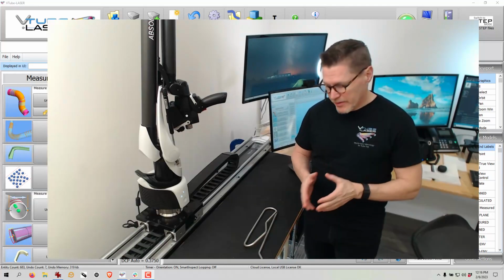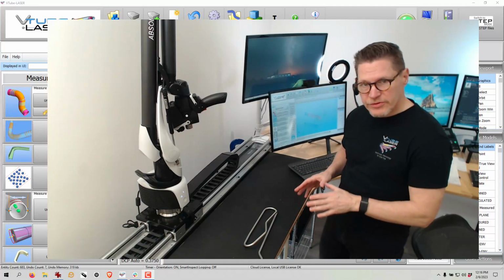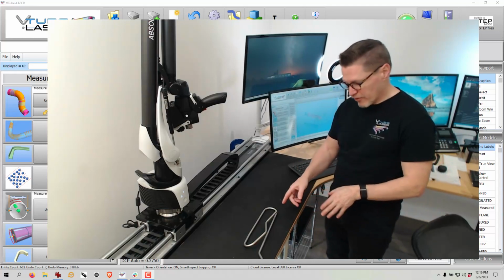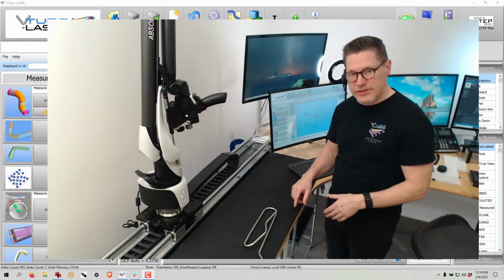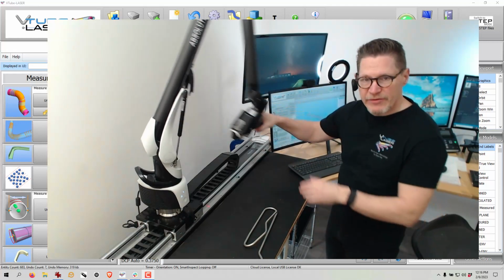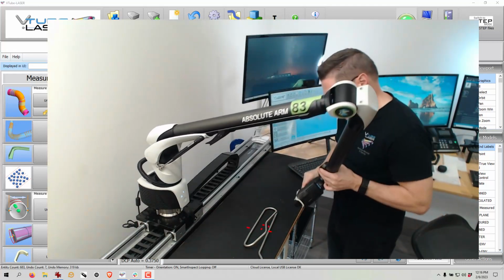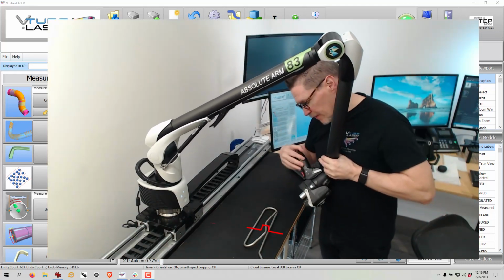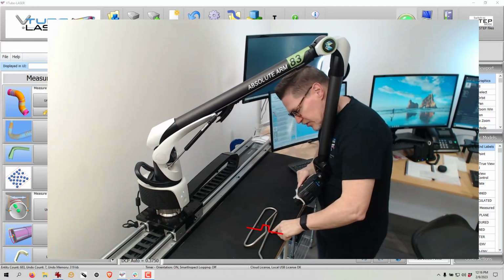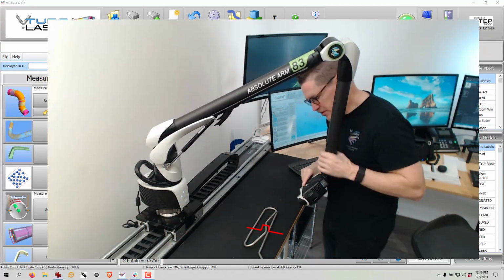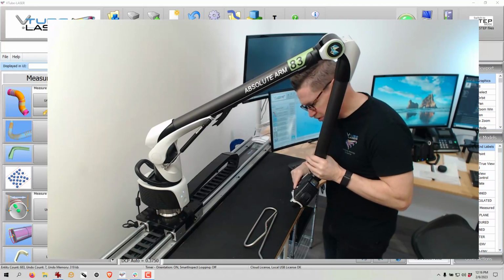In this video, I'm going to show you how to turn on and use the diameter cut plane for a part like this that turns back on itself. And part of the problem we have in a part like this is we have the laser line that strikes this straight and this straight and this straight simultaneously. So when we're scanning, we only want the straight we're pointing at.